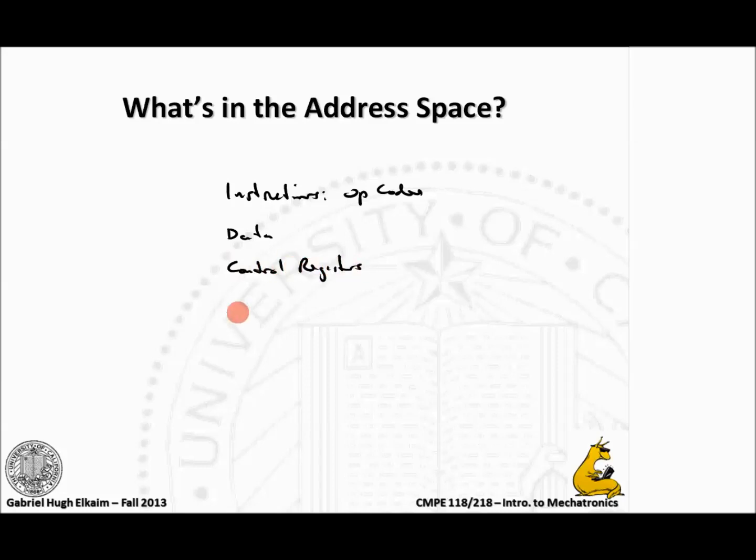We've got memory mapped I/O, which is how most people do it these days, and things like ports or pins. These just look like another area of memory. You write to it, and voltage is changed on a pin that's hooked to the external world. Same thing you can just read. For instance, when you read the A to D, you're reading what the voltage level is on that pin, and scaling it for you and doing some other nice things.